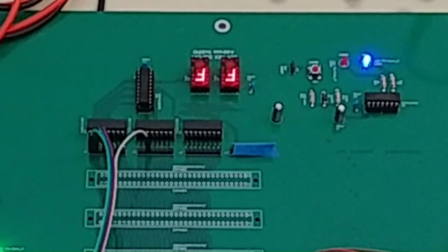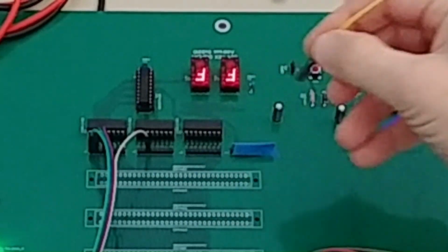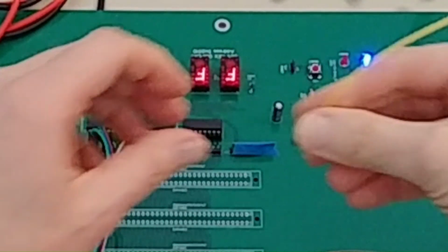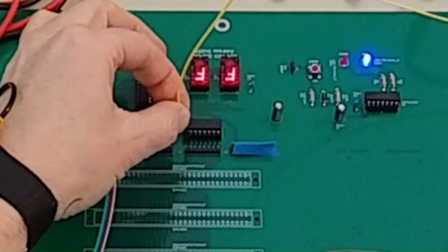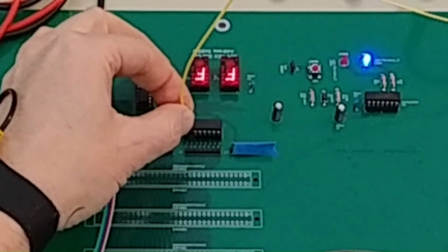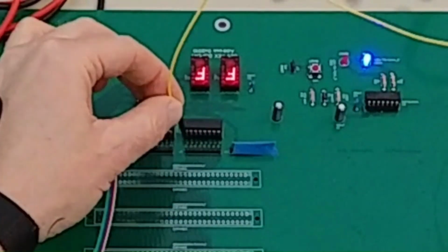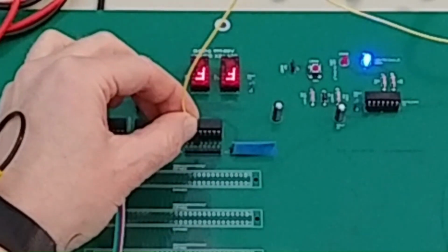Now, that's not what happened in the beginning when I did the first round of testing. What I saw was, even after I removed the U clock signal, the hex display was still updating, right? So I was getting this behavior. Whoops, get the right signal back patched in. All right, our write signal's in there. So even though I removed the U clock, the hex display was still loading. So I'll take the U clock out now, and we see the hex display is not loading.